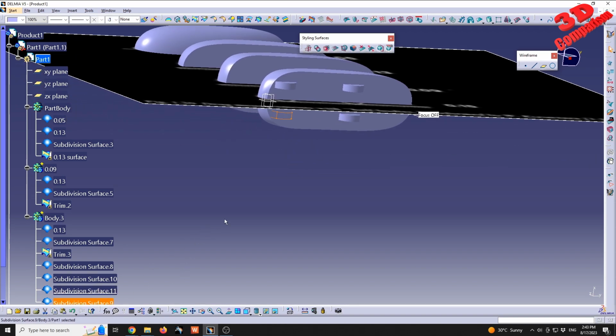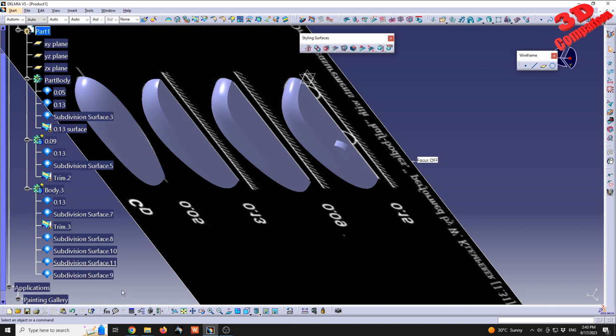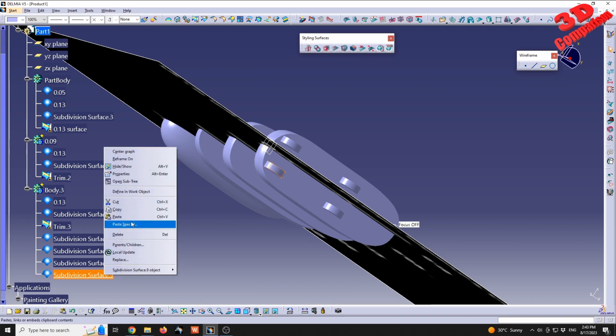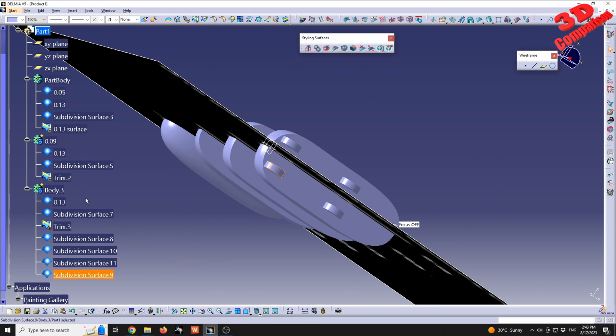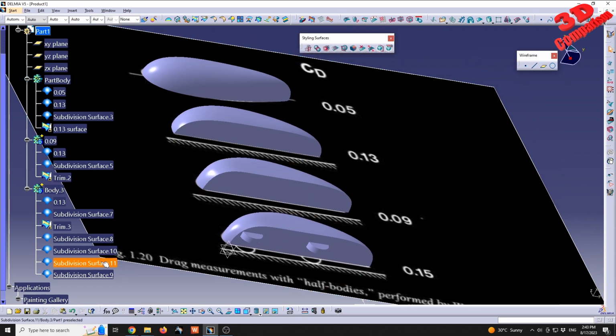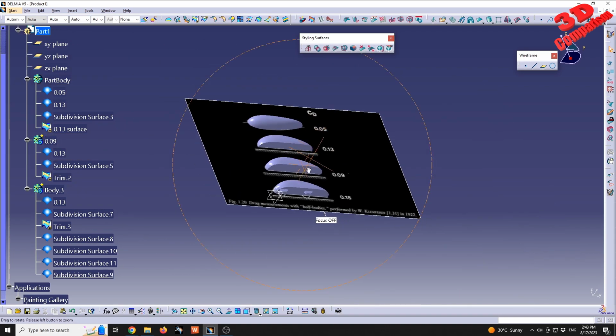Okay, I see that over here both wheels have been moved. So this is not visible. This is because I copy pasted those in front of Surface 9, and currently Catia is over here where we have that line. So I need to go to Surface 9 and define this as a work object. And that will also show the last part. So keep in mind this tip regarding defining work object, where exactly in time you want Catia to be. The main advantage is that you can go back in time in the tree and change those, and those changes will be done before those commands.